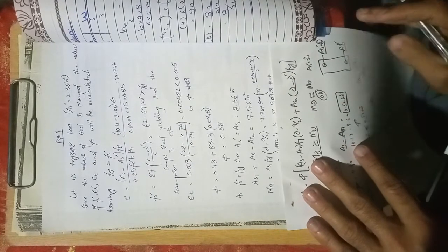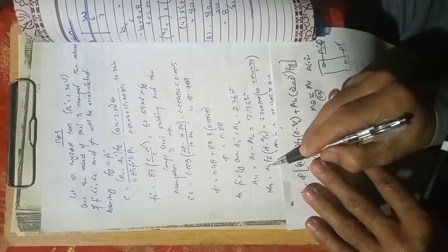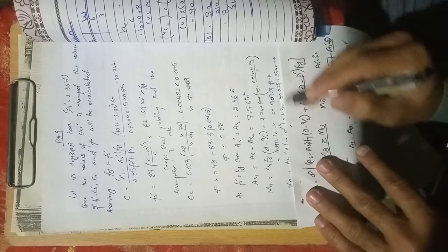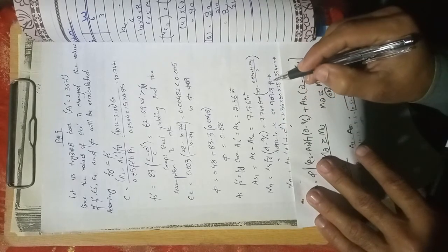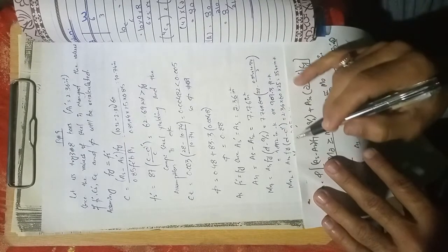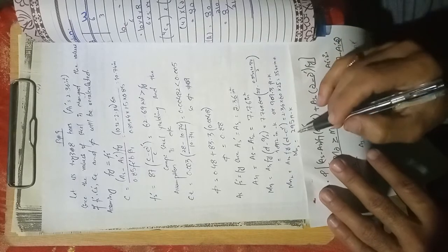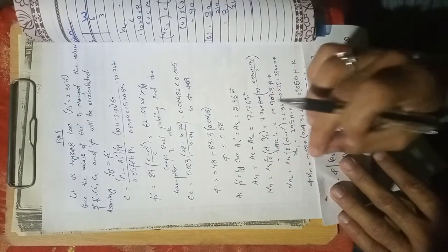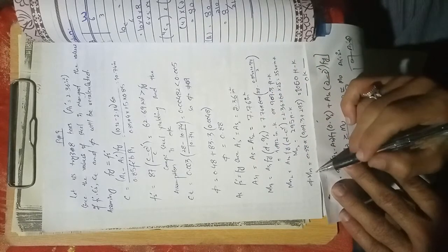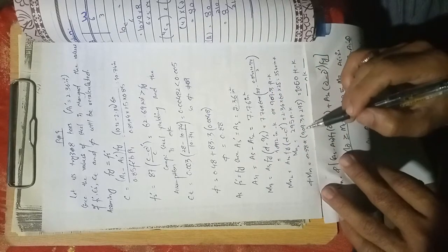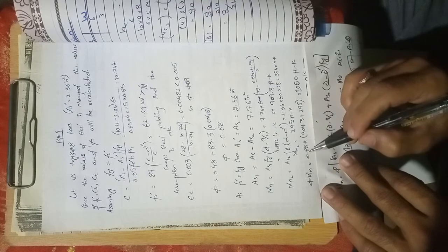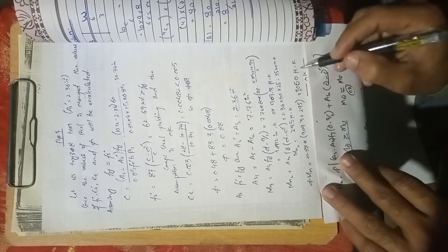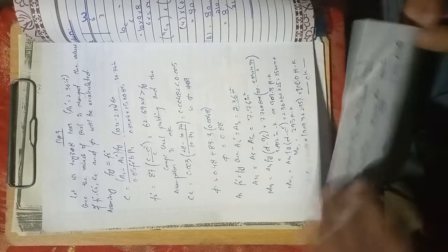So again, checking the moment capacity, Mn1 equals As1 fy. Again, this is Mn1, which equals 909.3 feet-kip, and Mn2, that is how much, 295. So just adding these two will give you the combined capacity, that is Mn1 plus Mn2, multiplied by the reduction factor, we got 1060 feet-kip. Now this time it is okay.